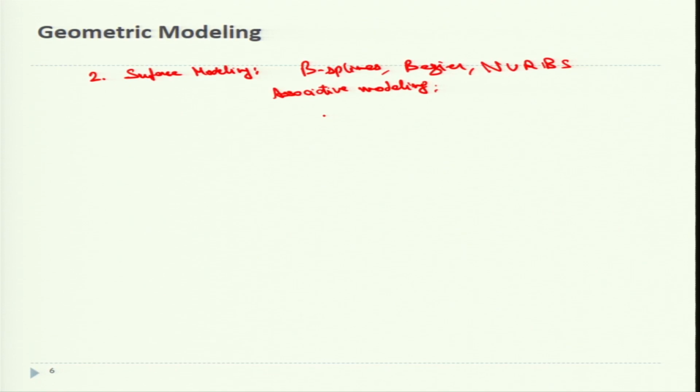Users can view all the surface points at once with surface modeling. Models are also imported from another CAD system occasionally, where features are lacking. In these situations, the desired changes can be made on one or more model faces by applying surface modeling techniques. Building one face at a time using surface modeling allows precise control over the contour and direction of any face. So multi-resolution modeling could also be developed through it.